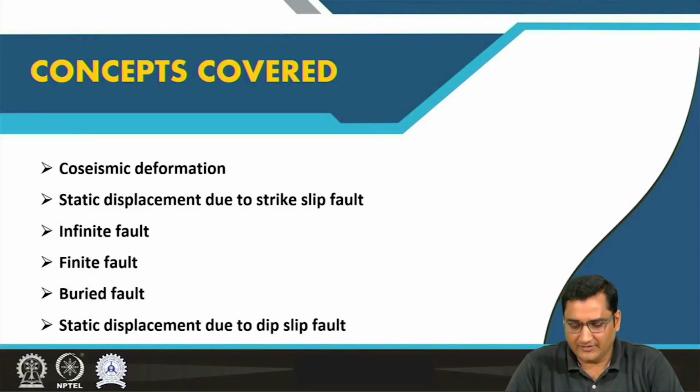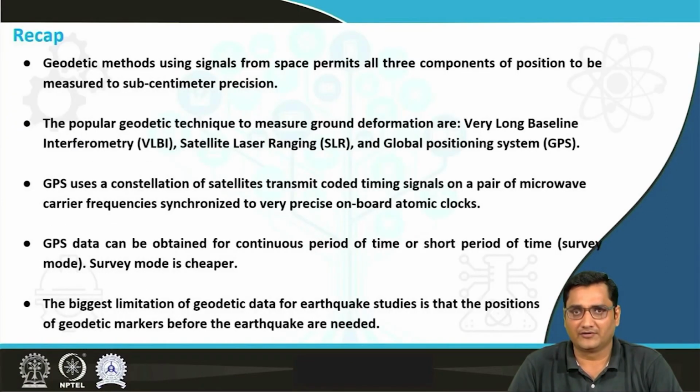In the lecture today, we are going to cover concepts such as co-seismic deformation, and then the static displacement due to a strike slip fault, and then we will see how the static displacement of an infinite fault is calculated. Then we will discuss the finite fault, and then the buried fault, and finally we will talk about the static displacement due to a dip slip fault.